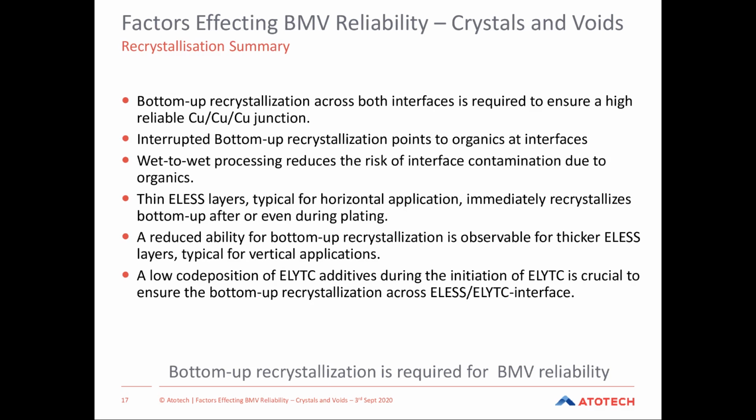Going from a wet, dry, wet process increases the risk of contamination. So a wet to wet is always a more preferable solution. And we see that thinner electrolysis layers are much better in terms of achieving this bottom-up crystallization than a top-down system that we get typically with thicker ones.